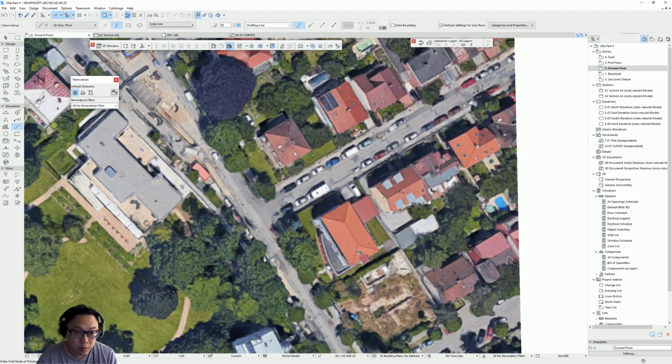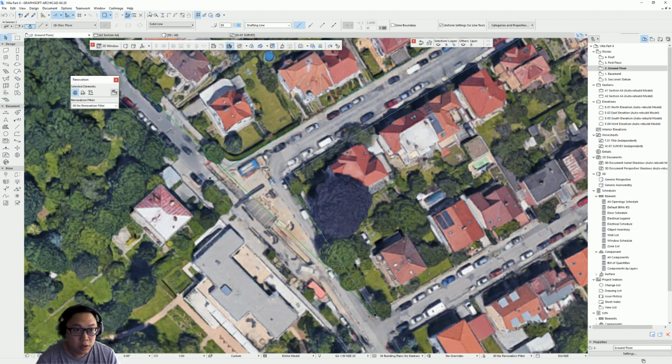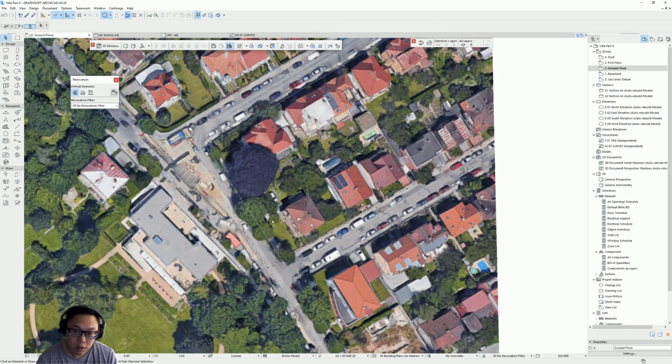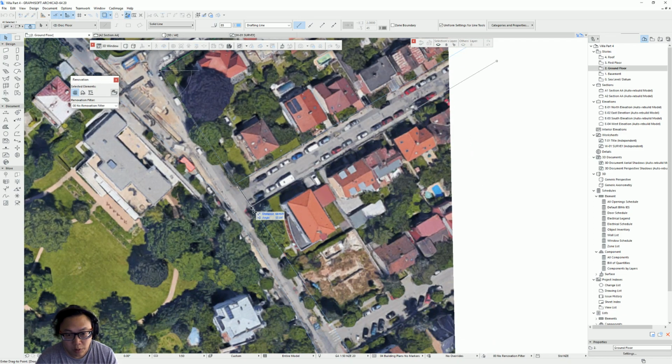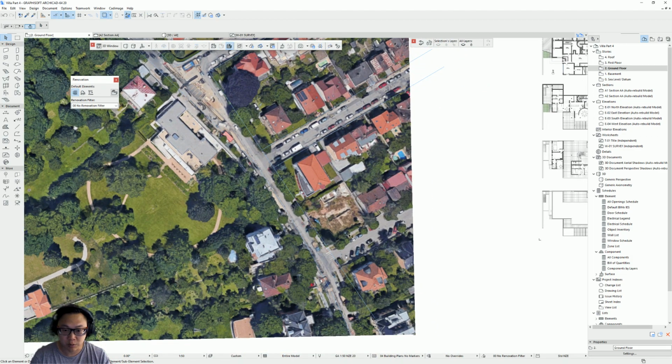Those two are going to intersect. Those two intersect, and I'm going to make a copy of this and drag it along that line. Press Shift to make it stick to this line. Make another copy. Pressing Control Alt allows me to do multiple copies during the same operation.